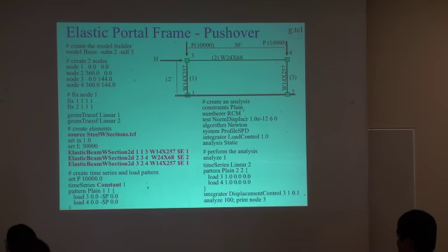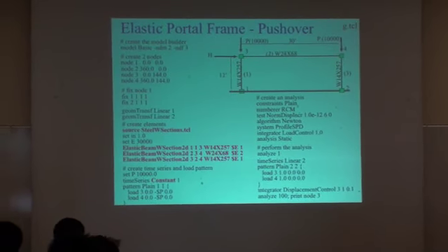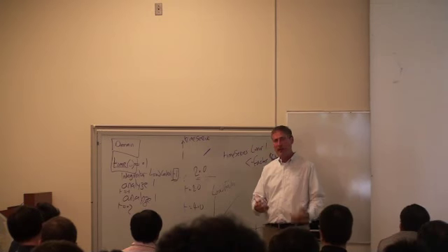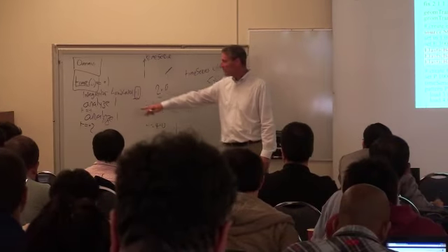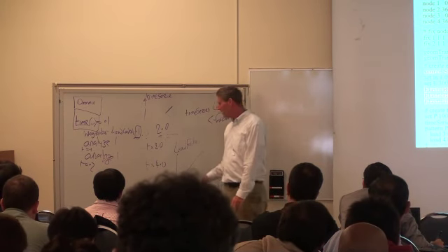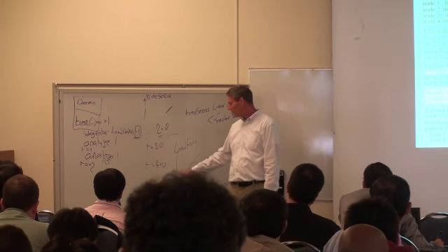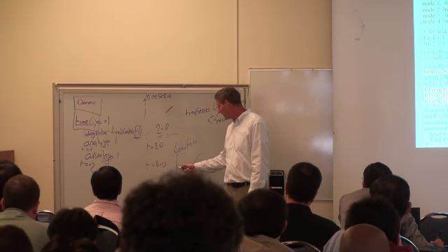What happens then to the load pattern or the applied load? They just depend on the time series. Say this is 0.2, and we have a linear time series, see? The slope was 1, so this will come back as 0.2. This is our time. This is our load factor. So we've got a load pattern in there that's linear with time. If we do 0.1, the load factor applied to the load would be 0.1. If we come in at 0.2, it would be 0.2. If the time is 2, the load factor applied to the load is 2. When we come in at 4, the load factor applied is 4. If this is a linear.